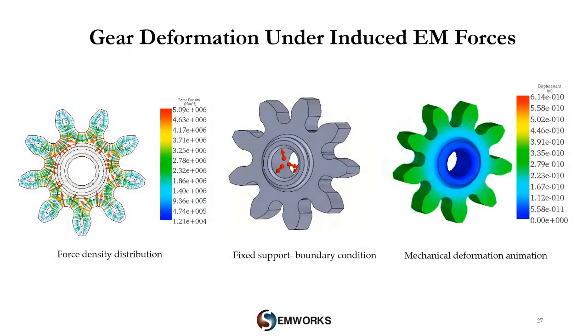Same thing for the heated gear. The force density distribution is shown by the left figure. Maximum forces are following the eddy currents profile, which are concentrated at the gear root regions. Now when fixed from the central hole, maximum gear deflections are localized across the teeth parts. Overall, under only the effect of electromagnetic forces, the attained stresses are relatively tolerable and acceptable.